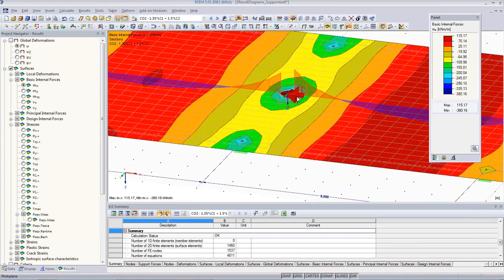First of all, the results are hidden inside the column because we assume inside the columns those results are not so relevant. Often it's standard practice that you make the design at the edge of the column. So we get the values at the edge of the column.